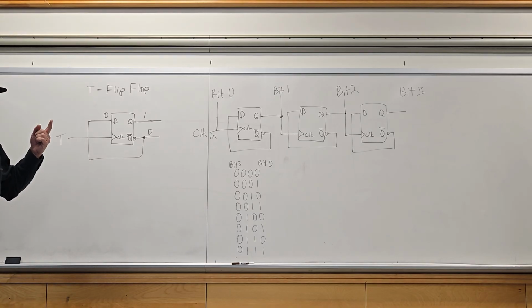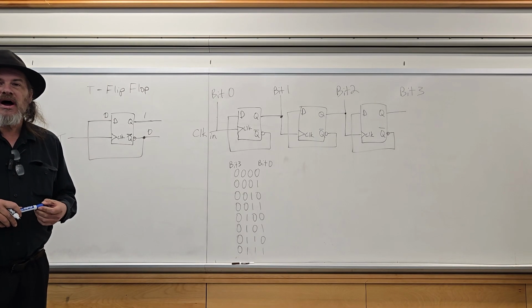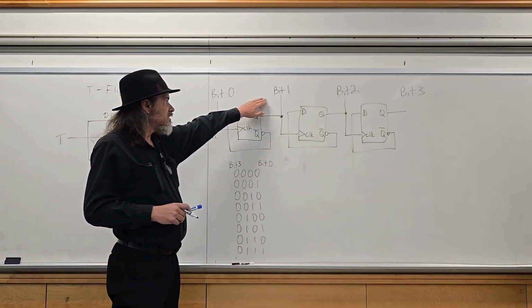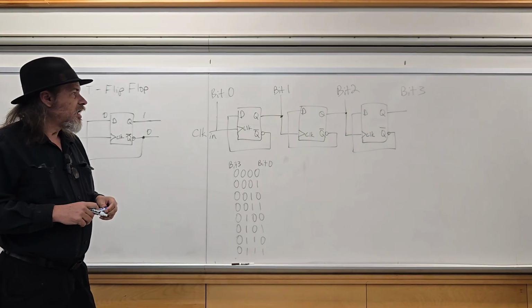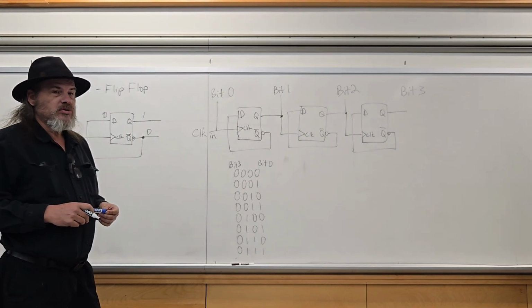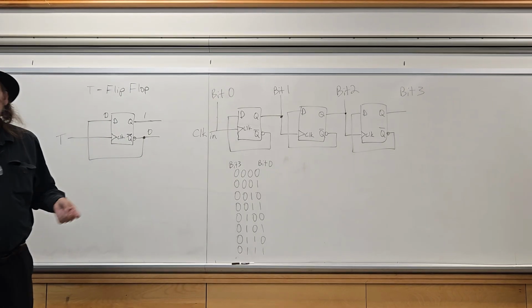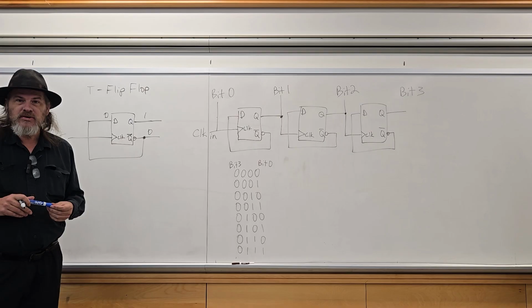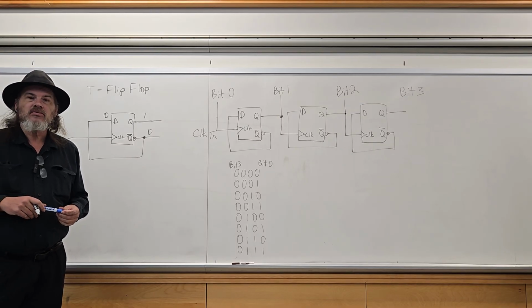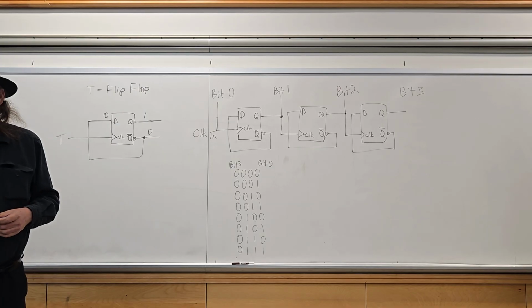You would have say an 8-stage counter or 16-stage counter that would count up 1 every clock cycle, and when these bits are equal to some predetermined value that you determine, it will take that long to count up to that number.